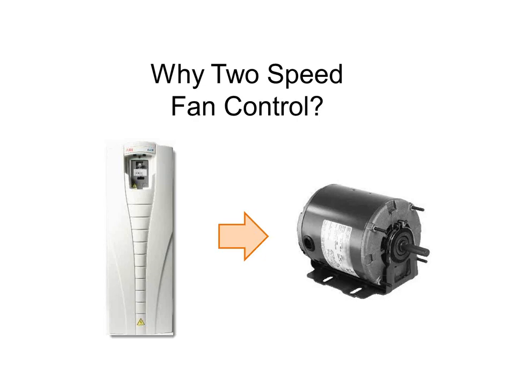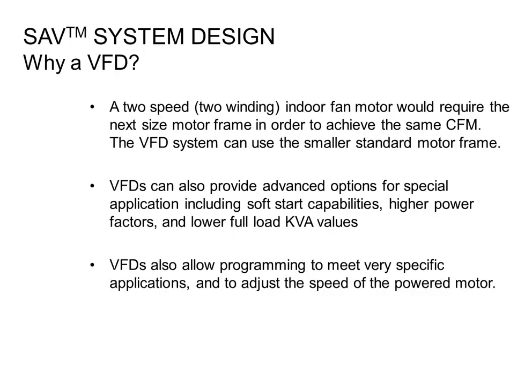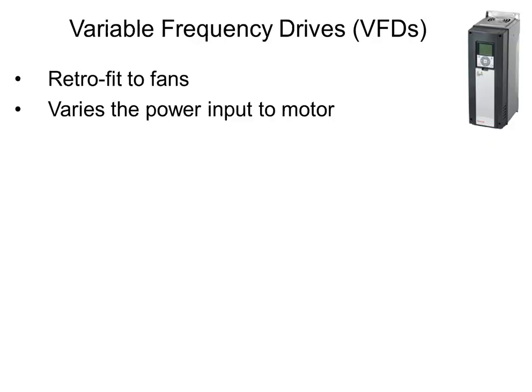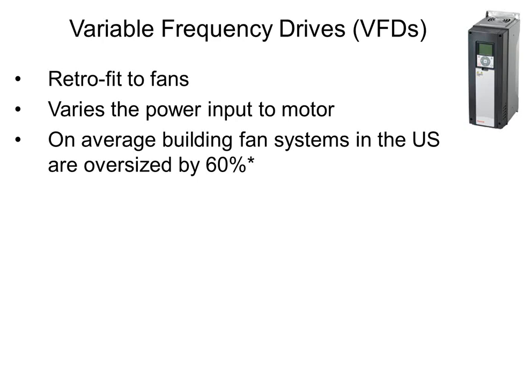I can get a VFD and a standard speed motor cheaper than a two-stage motor. So that's the main reason. Plus, it provides some other nice benefits like the soft start capabilities and lower demand charges when the units first kick on and those sorts of things. The quick spiel on VFDs, I'm sure most of you guys know. You've probably seen me talk about it before.